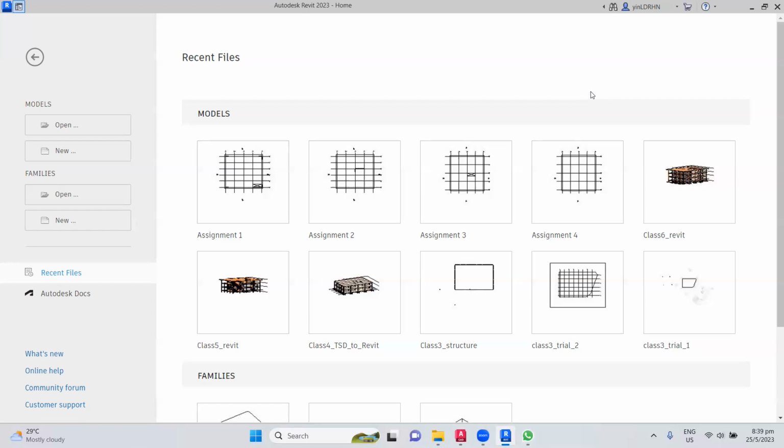So the depth is based on the rebar density. If you choose a smaller size, you have to put more rebar. If you choose a bigger one, you put less rebar. But if you choose something very deep, it's not practical. So choose a member size and start to do the modeling.